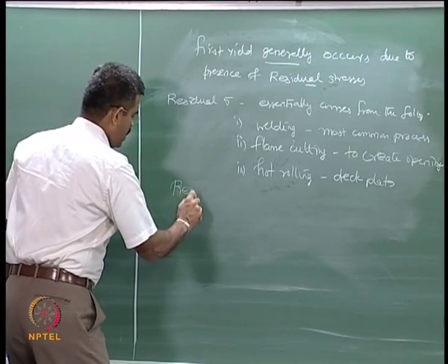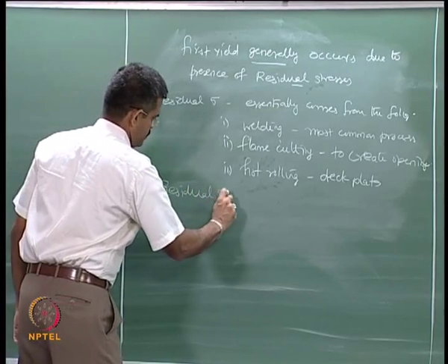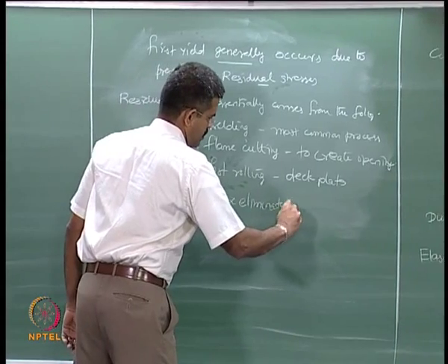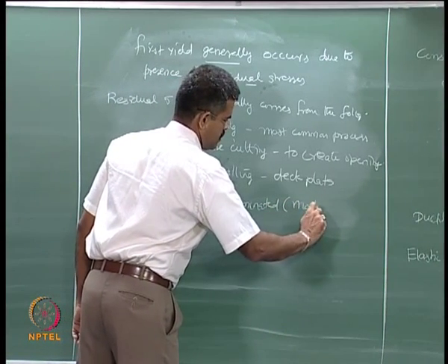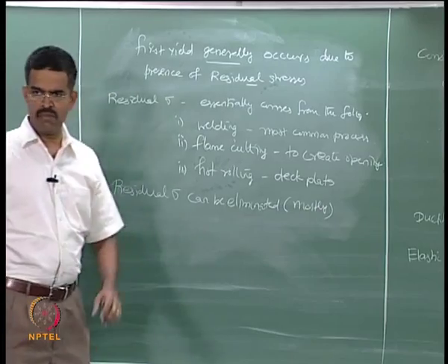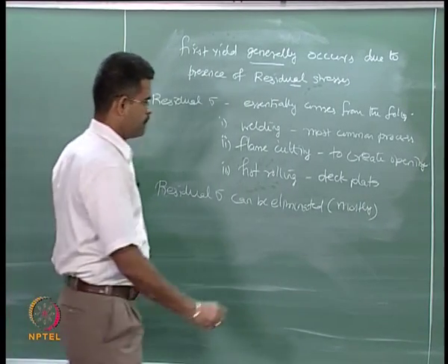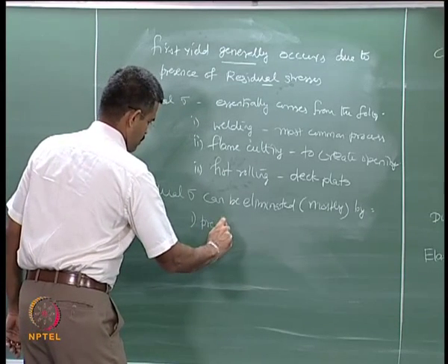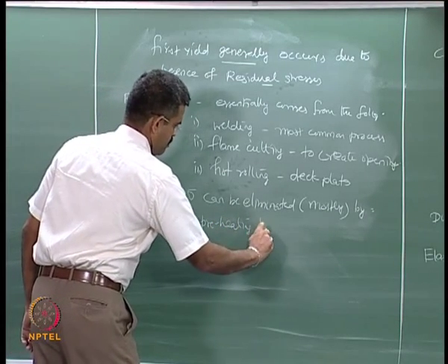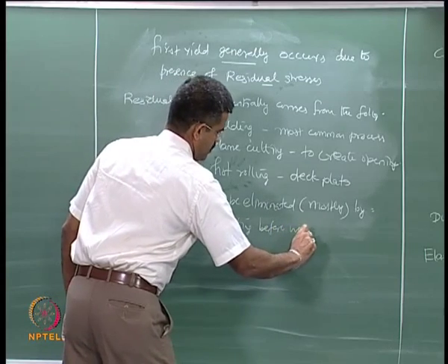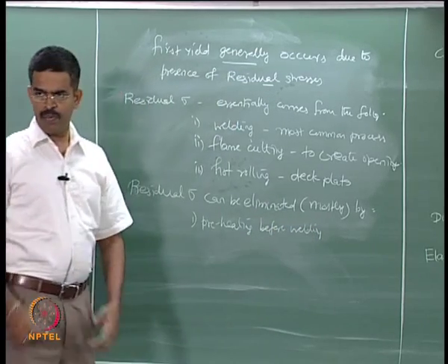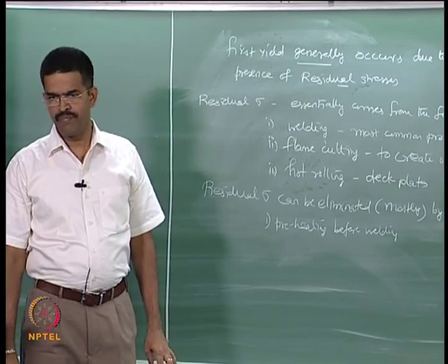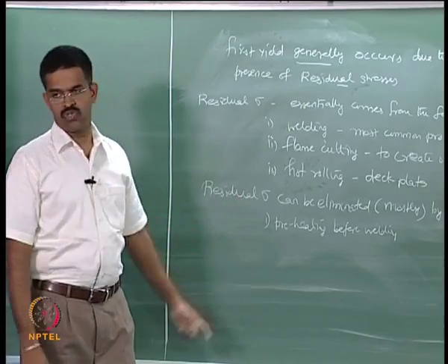Residual stresses can be eliminated, not completely, but I should say mostly, by preheating before welding. If you preheat the member before welding, you can reduce the residual stresses.